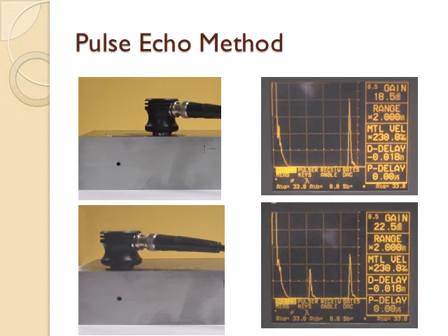So the defects, due to the change in medium, give rise to another signal, and name it as pulse Z. It will occur in between pulses A and B. Similarly, if we have many such holes, many Z pulses will be seen on the screen. We can see that in the CRO. From the time delay between the transmitted and the received pulses, the position of the hole can be found.